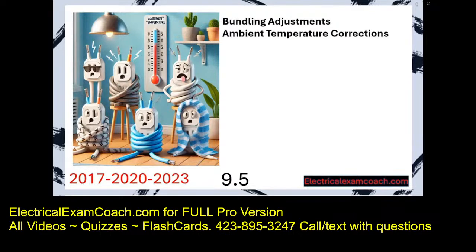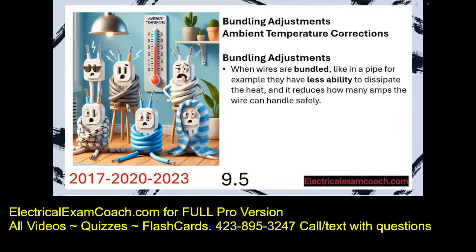And remember, ampacity is just how many amps the wire can handle safely under its conditions of use without exceeding its temperature rating. Bundling adjustments work like this. When wires are bundled, like in a pipe for example, they have less ability to dissipate the heat, and it reduces how many amps the wire can handle safely.